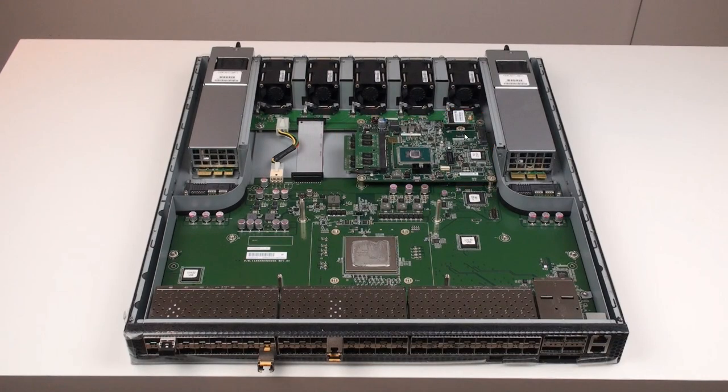All right, so now as you can see, I have removed the heat sinks, and this is the Broadcom Trident2 chipset under that massive heatsink. And all of these ports, as you can see here, are connecting directly to the chipset. There is no PHY interface because these are just SFP ports. The SFPs which are plugged in have their own PHY, so there is no need to have a PHY chipset on the switch itself. And the communication between the CPU board and the main switching chipset, the Broadcom Trident2, is via PCI Express. And there are other components.